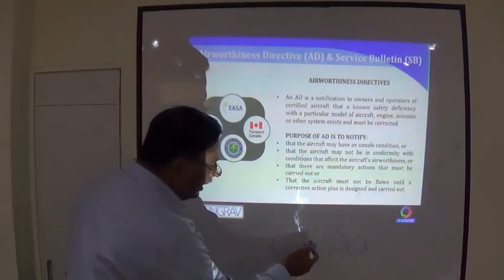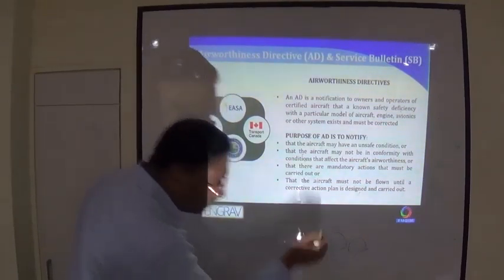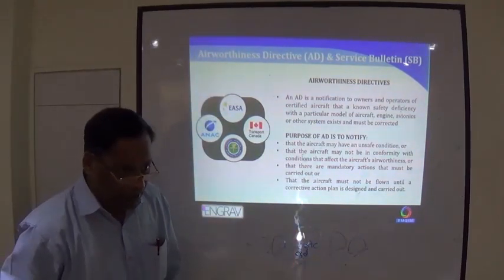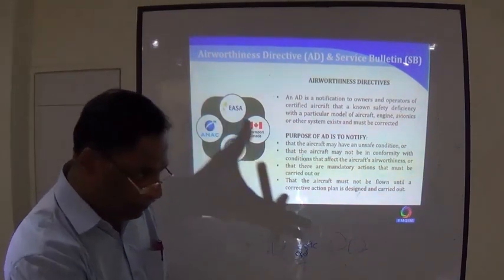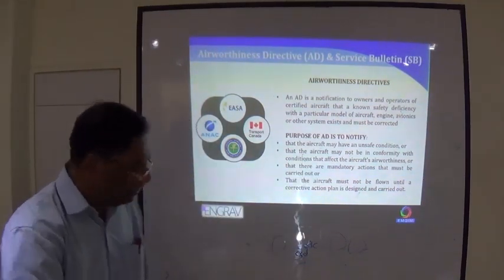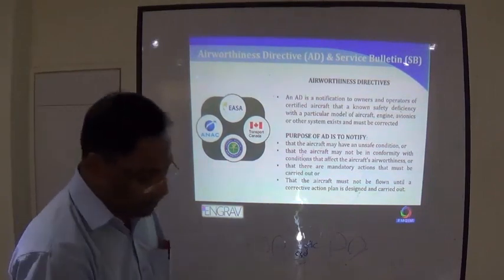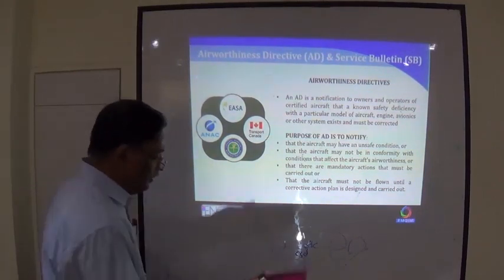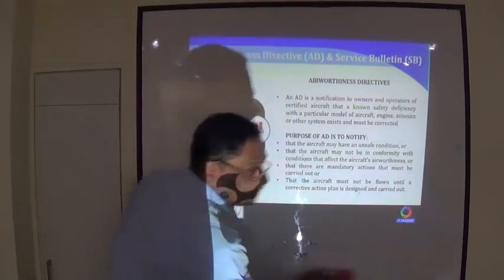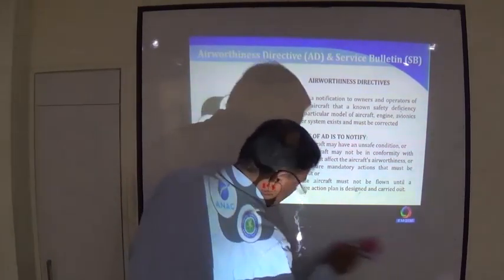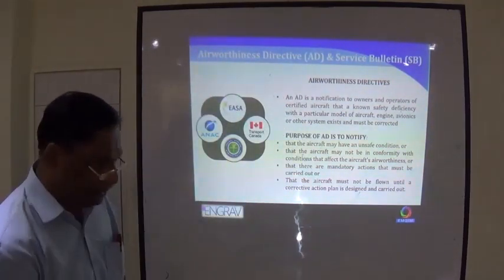If the metacenter goes below the CG for some reason, the ship will topple. It will not capsize immediately, but out at sea, when the weather is bad or something, it can capsize. So in the ships we used to calculate it every day.